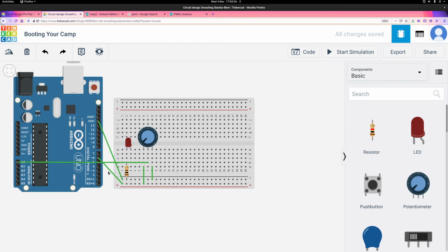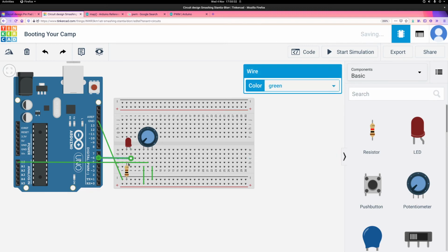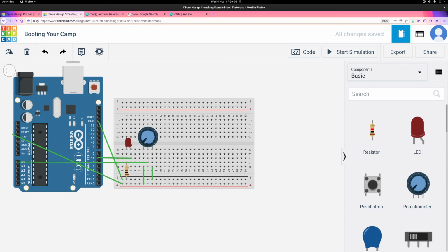So we'll get rid of that wire. This will no longer go to the whole power of the board, but 6 instead will just power this LED. So 6 is just powering the LED, and then I'll connect this just to constant positive 5-volt power. And that should work all right.